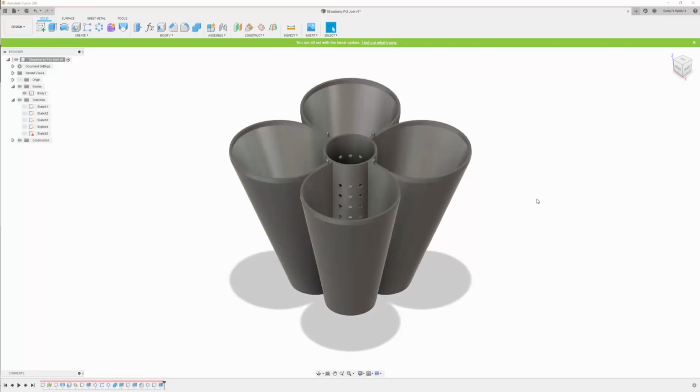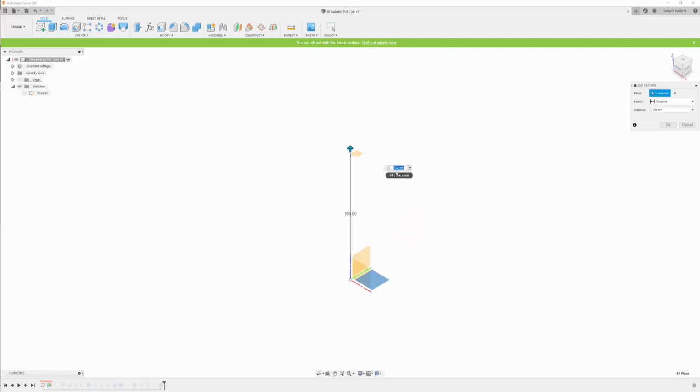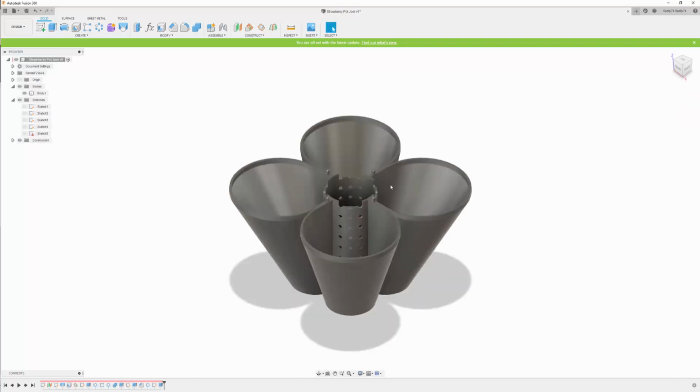Okay, Joel, looking at your model, which I've basically modeled exactly the same way as you did on your YouTube video, the big problem comes into it when you start to make some changes. So for instance, if we change the elevation of the object from 150 down to 105, for instance, and we finish that, because of the extrusions we've got with all our holes, we start to end up with some really ugly results here.